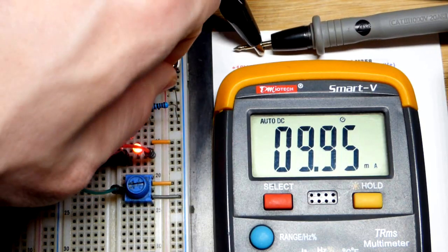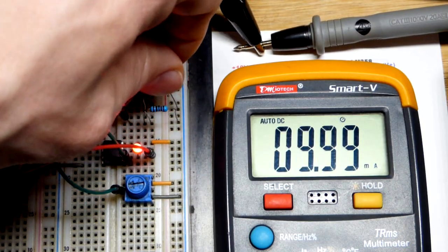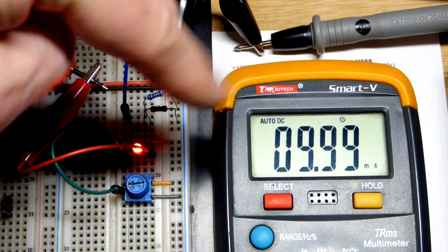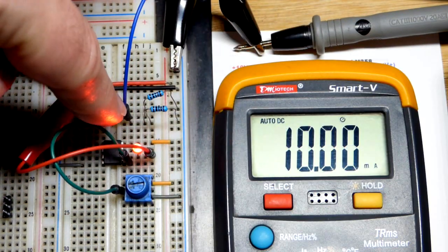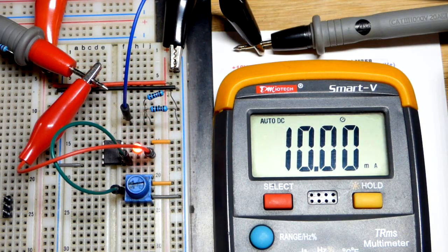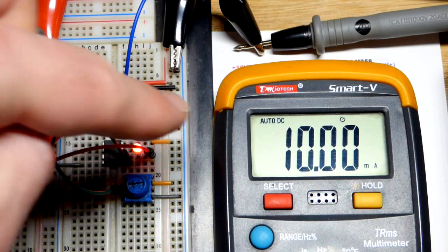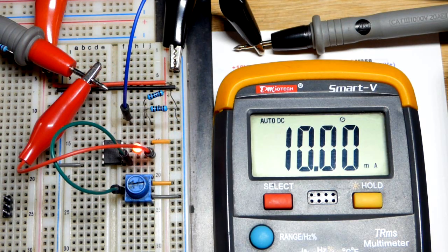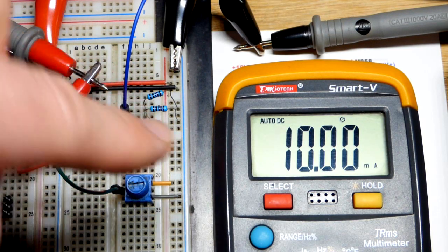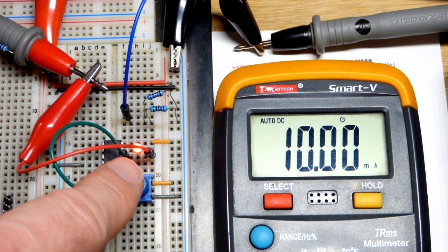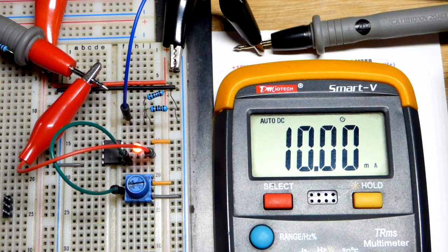So now each resistor is connected to that jumper there, going through the multimeter right there. And then each resistor is also connected to ground right there. So half the current's going through one resistor, half the current's going through the other resistor. They're both 5 milliamps of current, but both of those currents also have to go through the meter and the LED, everything else right there. So yeah, we got 10 milliamps of current right there.